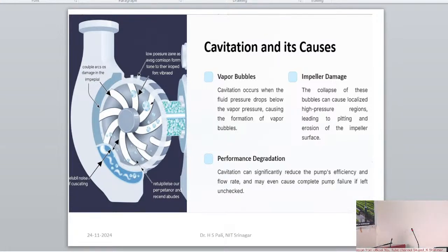So maximum efficiency is 73%. There is a curve like this, 72, 65, 50. So this is the important part. If you want to maximize the efficiency, then it is not possible to gain the maximum head. So optimize both parameters, optimize the head and efficiency.